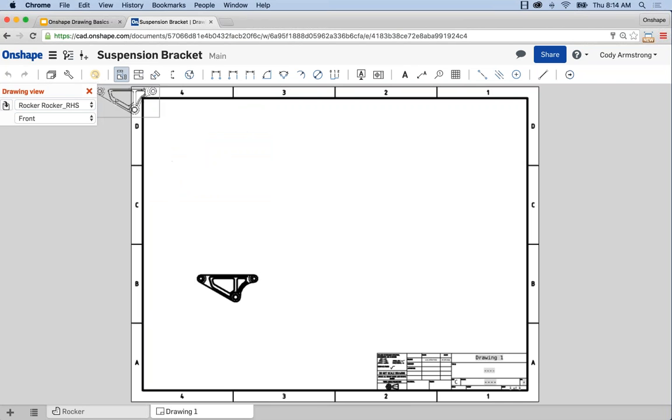Okay. And then I choose the orientation that I want. This is for your standard drawing views, front, top, right, isometric, and so on. So you can choose your standard drawing views and place them, much like I did with the very first one here. But I want to show another technique, and that is the next icon over, the projected view command.